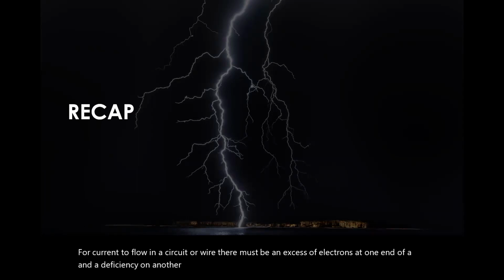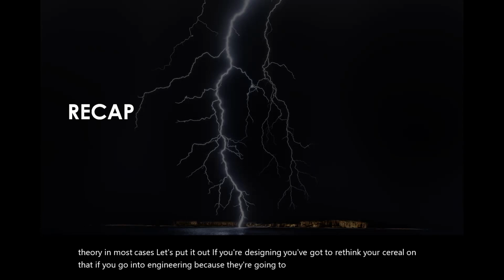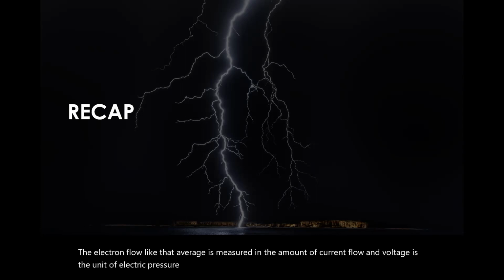Okay, automotive electricity uses the conventional theory in most cases. If you go into engineering or design, you've got to rethink your theory on that, because they're going to get back to the electron flow. Amperage is the measure of the amount of current flow, and voltage is the unit of electric pressure. Ohms is the resistance to electric flow. Sources of electricity can be friction, heat, light, pressure, and chemical. There are a few other ones out there too, but that's pretty much what you use in the automotive field.